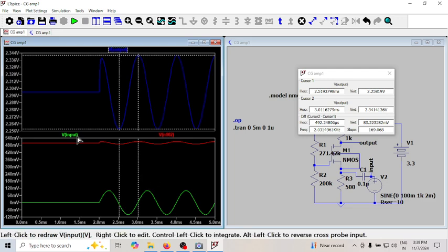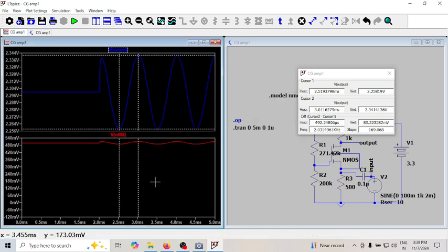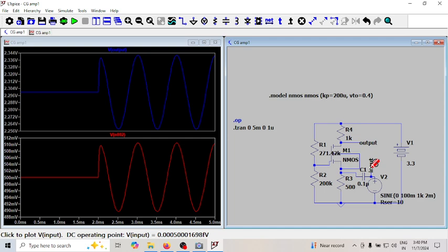Now let me take this out totally, delete this cursor. Okay, I'm having only this. This is the actual input voltage that is reaching the amplifier. So this multiplied by 4 times I'll get the output, because this is the actual input. Even though I have an amplitude of whatever the signal, how much is reaching over here matters. So this signal is amplified by 4 times. So that's what I'm trying to see now.